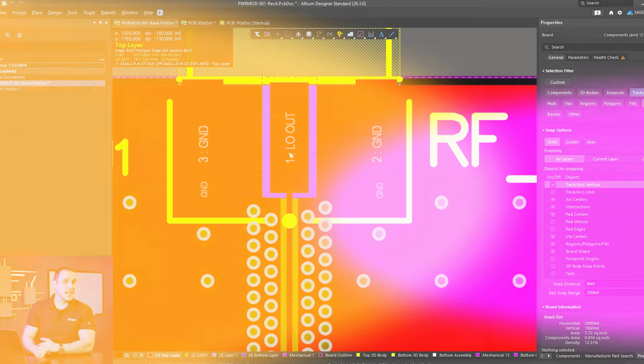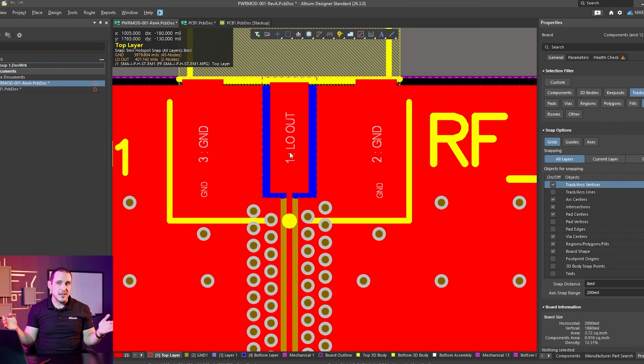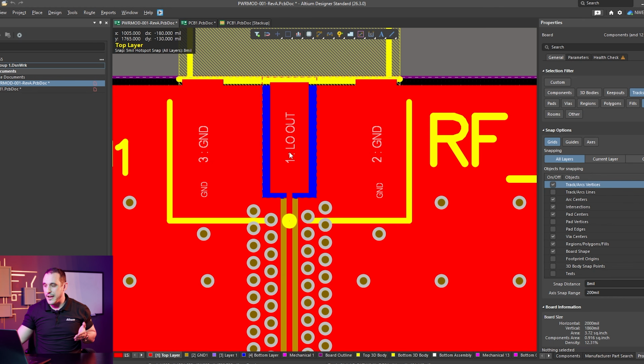Now for this specific design, we actually did this in a video from a couple of years ago. And if you go take a look at the link in the video description, you'll see where we actually compared the case with the taper to the case without the taper. And we found that this design actually functioned just a little bit better when we didn't use the taper in this layout. Now that's not going to be the case for every PCB. In some cases you might do the simulation and you might find that you need to have a taper in between this large pad and the narrow trace in order to bring your insertion loss down sufficiently low within the frequency range that you're targeting.